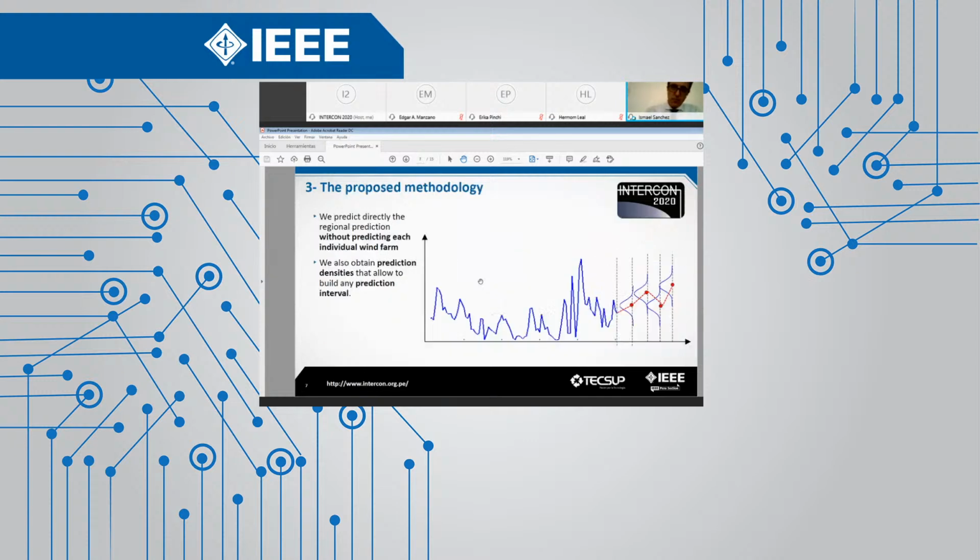Well, what do we propose? What we propose is to obtain the regional wind power predictions directly, without having to predict each individual wind farm, because in that step you are committing an error. So you add them up, you are aggregating errors. Also, we not only avoid predicting any individual wind farm, but we also supply not a single point prediction, but a whole distribution, like you see in this chart.